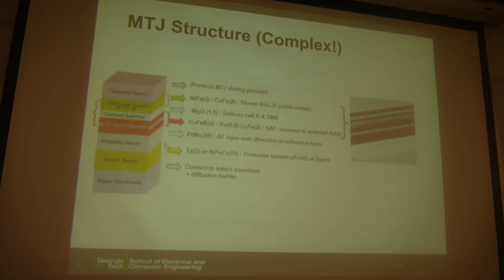So it's very complicated. The material system typically uses ferromagnetic materials, so you will involve cobalt, iron, those magnetic elements. And the tunnel barrier is typically MgO, 1 or 2 nanometers of very thin oxide. This is a TEM image. You can see different layers under the microscope, and each layer is typically very thin, a few nanometers. So the fabrication is not easy for this MTJ structure.